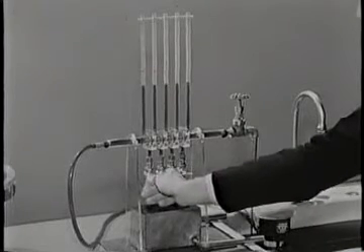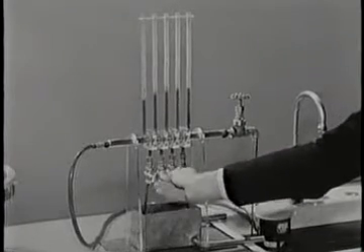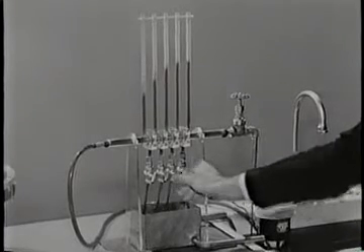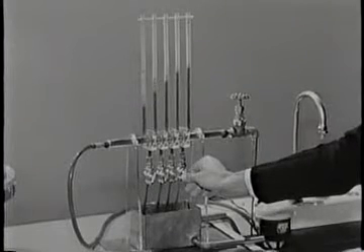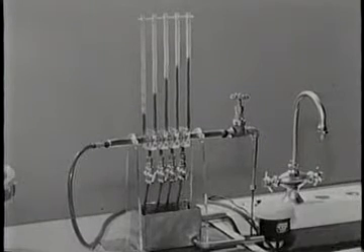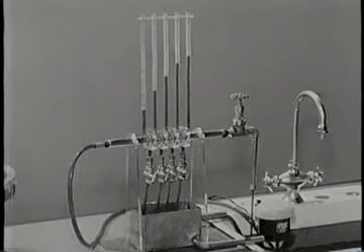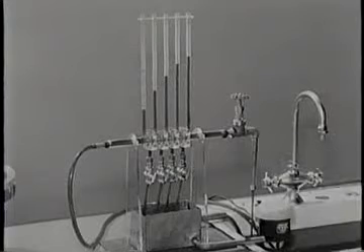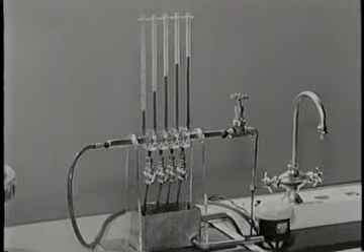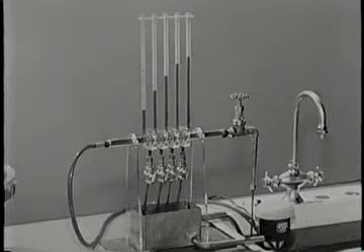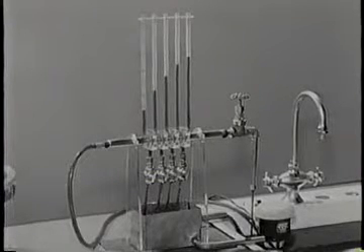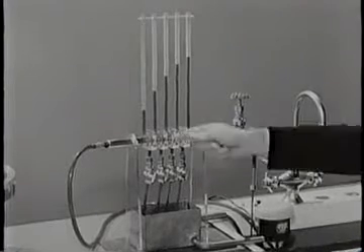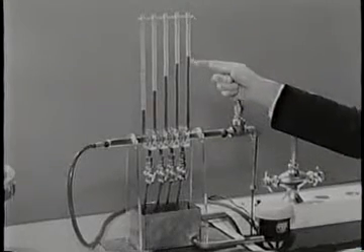I'll reduce the volume flow at successive sections by bleeding water from the manifold. The pressure now rises. Since the area is constant, the velocity is proportional to the volume flow. Therefore, the velocity decreases. It is this streamwise deceleration which produces the streamwise rise in pressure.